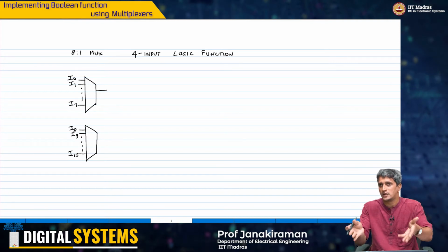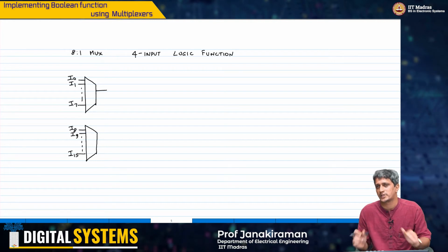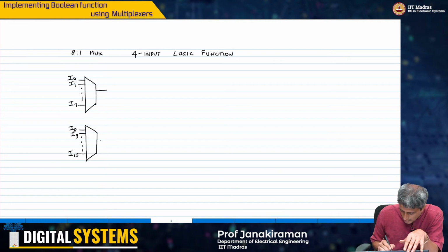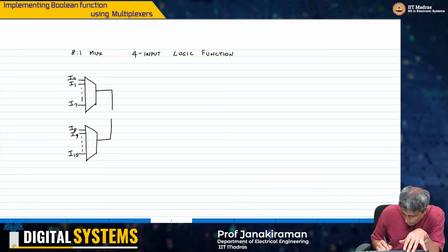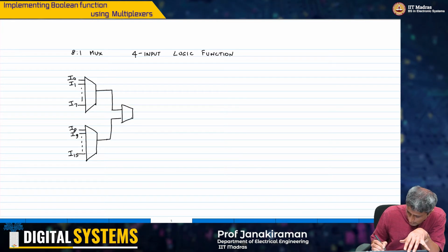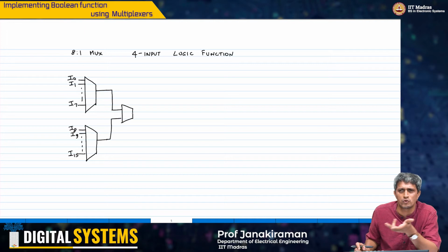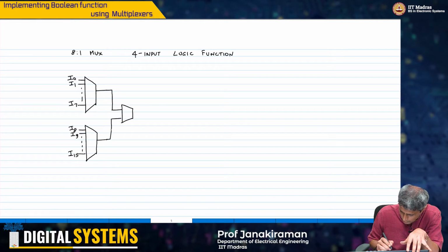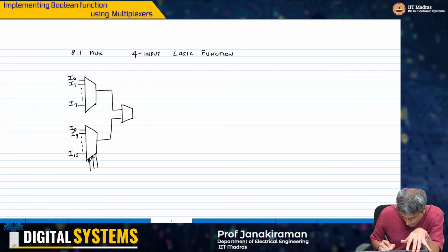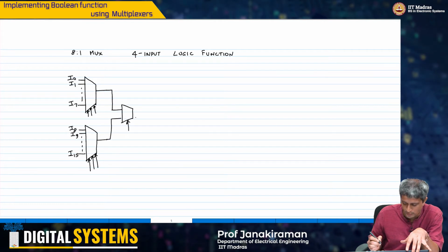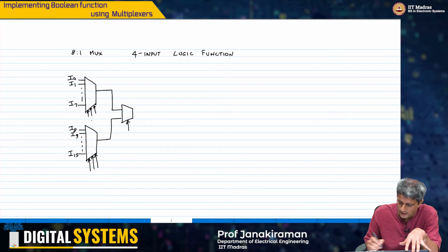Then I can do what I just discussed in the previous case for that XOR 3 implementation, right? So then I would basically take this and then implement a 2:1 mux using the 8:1 mux. All I have to do is ground the other inputs, right? So I will just assume that I have this case here, select lines are here, and then this is my output, right?